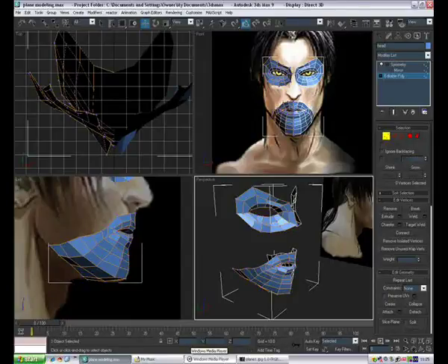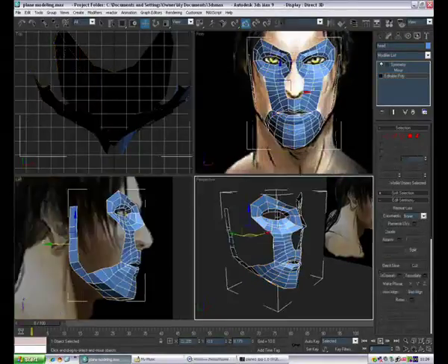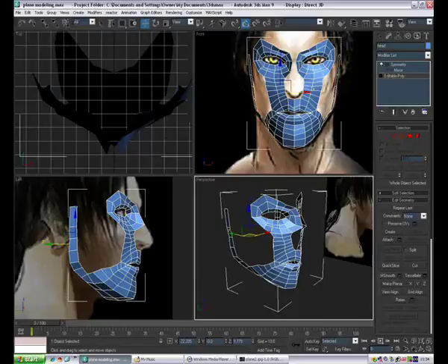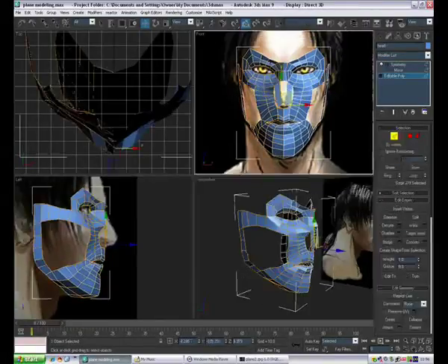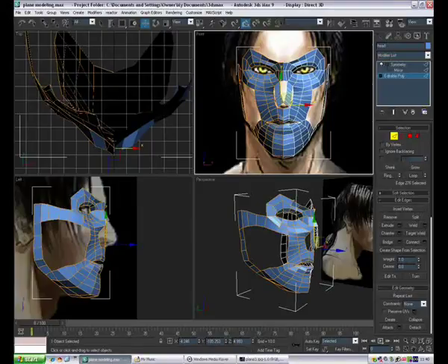And here we've selected all the bottom edges along the mouth and shift dragged them all down and matched them so it defines the chin, back to the jawbone. Here we go up with one plane up to the side, up the jawline, and also down, I've bridged from the eye to the mouth. Here we've connected the eye to the back of the jawline and just created some more faces ready to define the nose.